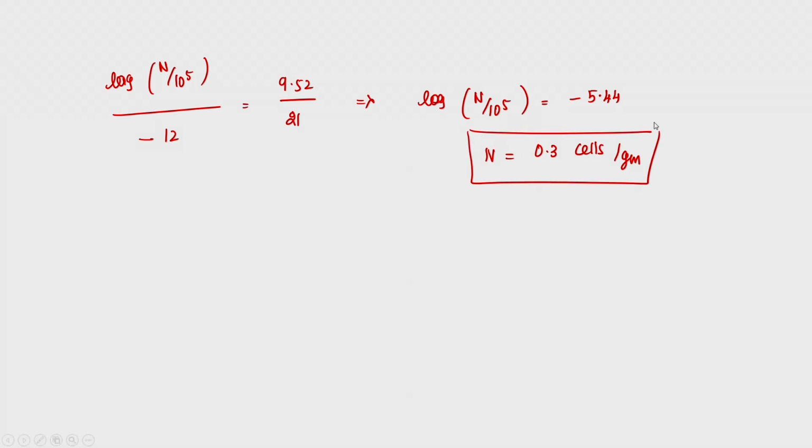right. For the reference condition what they have given is 110 degree centigrade, if you maintain 21 minute, you can reduce 12 log reduction. So, that means if my initial spores are 10 to the power of 12, you can reduce to 1 spore. So, this is the process as a reference.